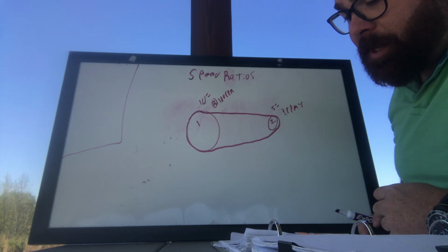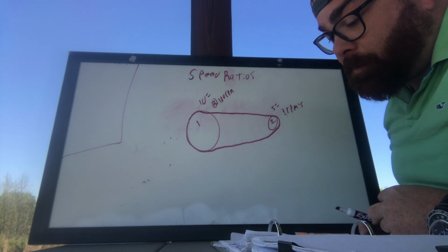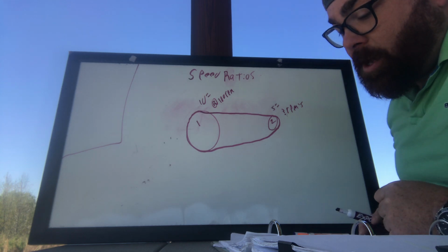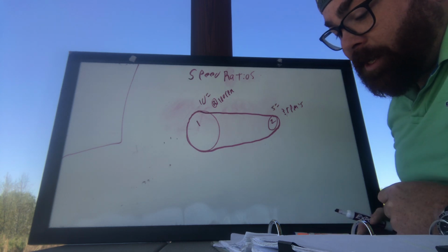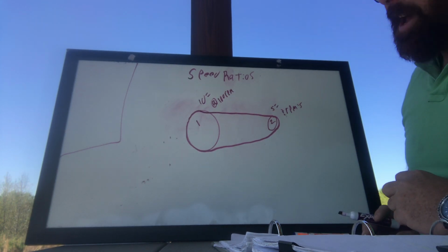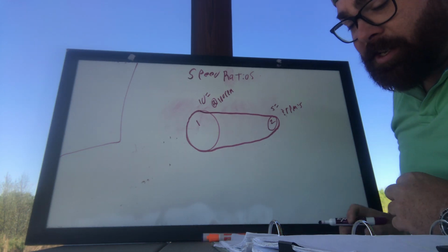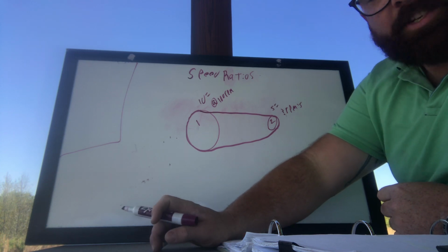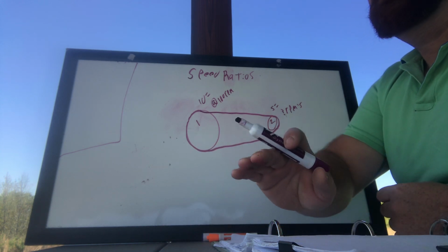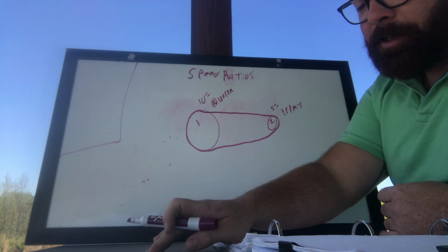As previously stated, the difference in speed is a function of the ratio of the gear diameters. To state this another way, the product of the speed and diameter of a pulley or gear is the exact same as the product of the speed and diameter of the pulley or gear which is connected. If you're in my class, you've heard this tons and tons, that we're going to use this kind of base formula: a measurement and a force equals a measurement and a force.